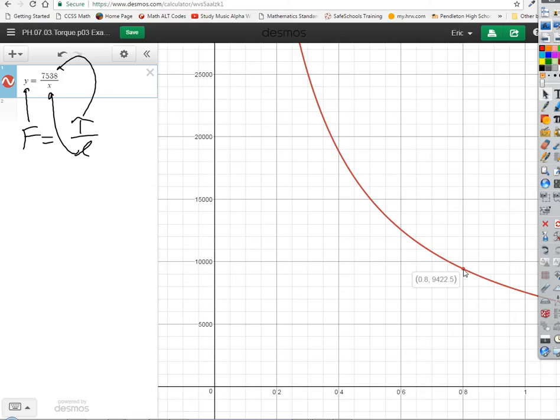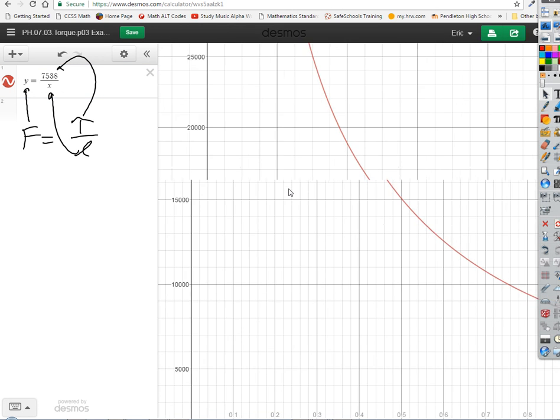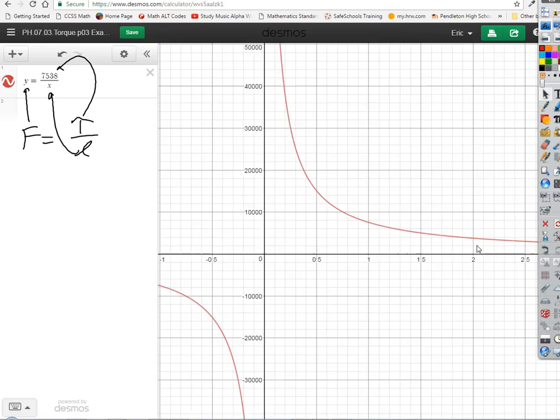I don't know if that's realistic or not, but if we make this a lot smaller, if we go back, for example, to something like 0.2 of a meter, then it'd be 40 centimeters across the whole tire. That's not very big. It's a pretty small tire, but look at all the extra force we get out of that. We get almost 38,000 newtons compared to, where were we before?